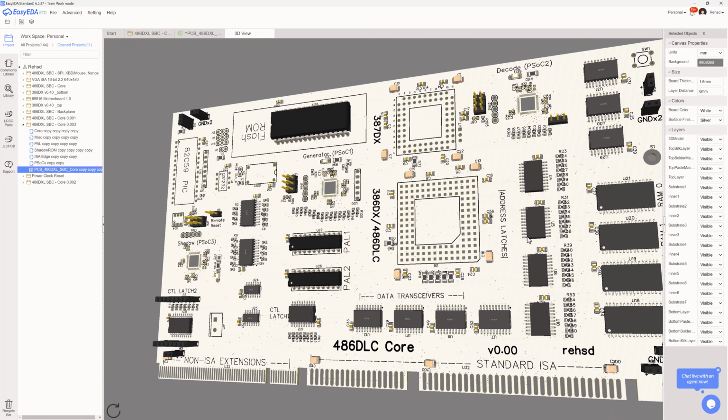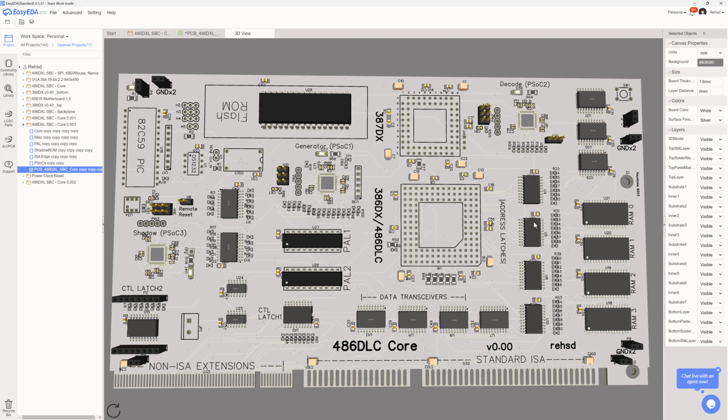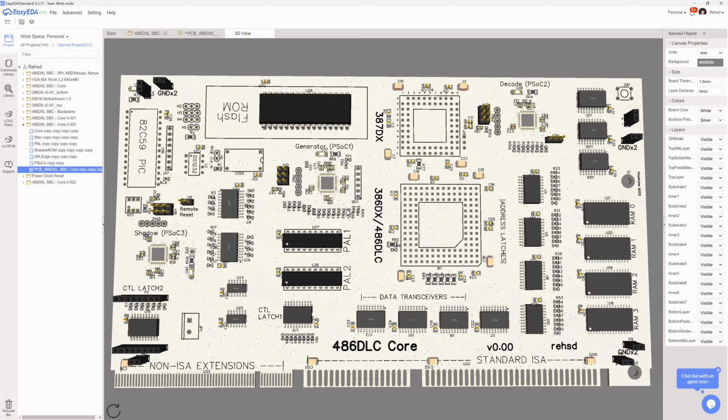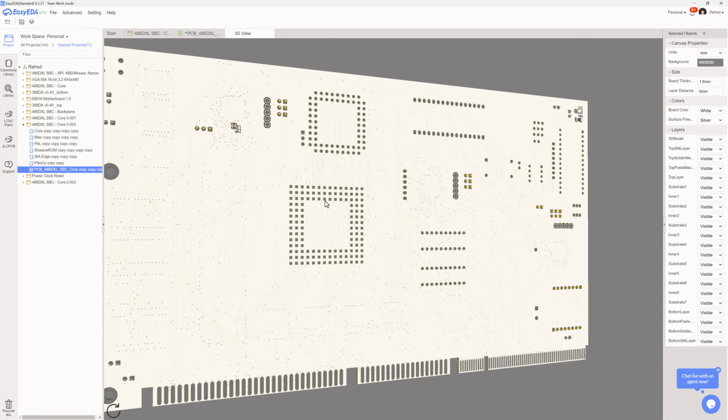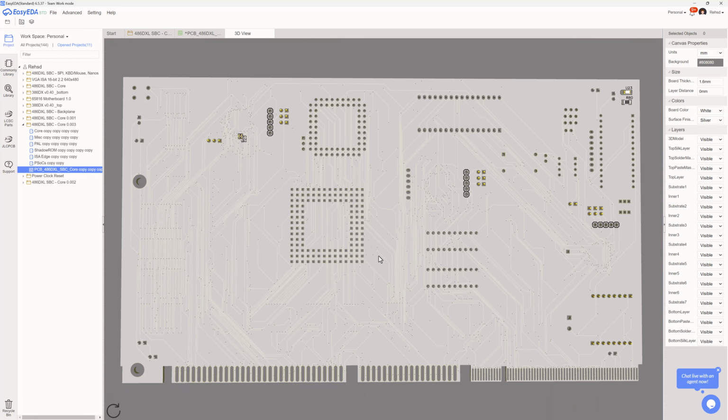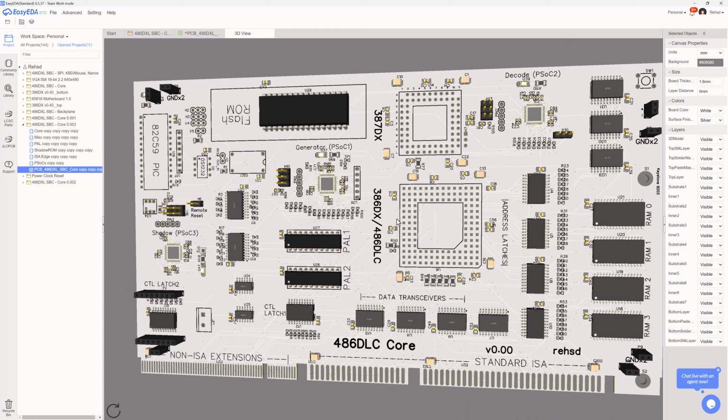And it just got to be too much. And the routing was quite messy to try to make that work. And then I also thought about, I'll call it manufacturability and serviceability. To actually lay out this board with the inner copper in it, I expect I'll probably be using my hot plate to at least warm up the board a little bit, and then I'll use my hot air gun to actually do the soldering. And for me, that got a little bit of a concern if I want to have components on both sides and want to use the hot plate and hot air soldering station.